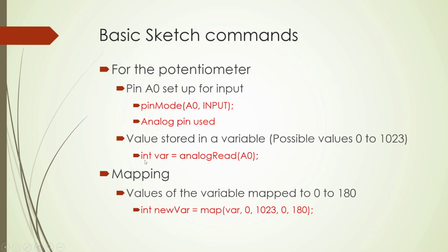The value is stored in a variable. So how is the value stored into a variable? We say int var. Var is the variable that has been created, and we give the command analogRead(A0). So whatever is connected to A0, the value is read from there and it is stored into the variable var.